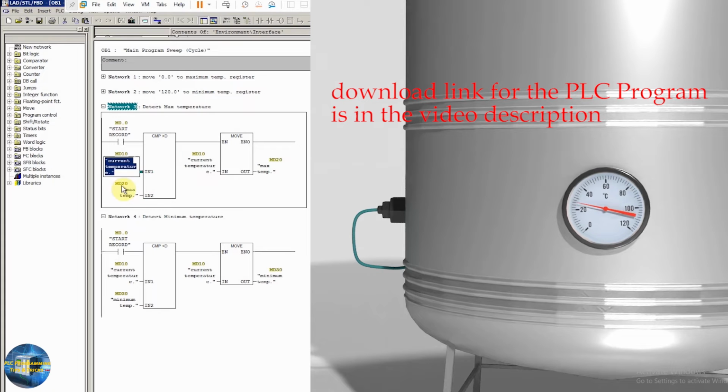Now both are the same, and let's suppose that after some time the temperature again increases and reaches 20 degrees. The 20 degrees temperature is more than the 15 degrees value which is in the maximum temperature data register in MD20. So again our comparison command will become true, and again it will activate this move command. It will move the current temperature, which is 20 degrees, into the maximum temperature data register, and the same will be updated here as well.